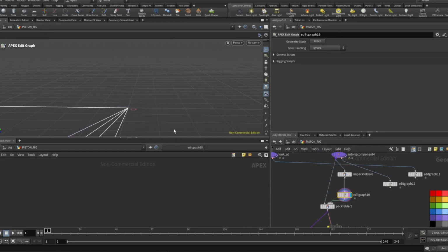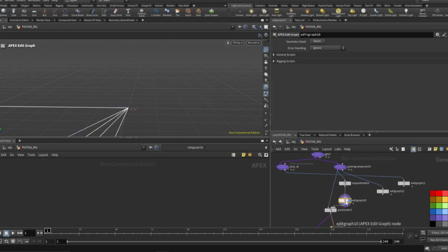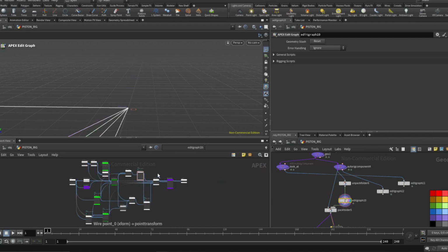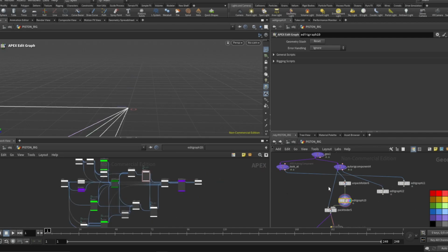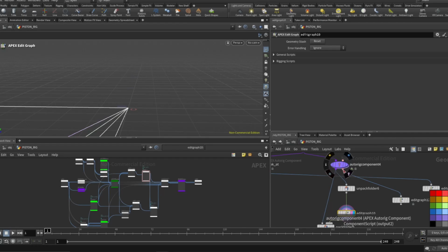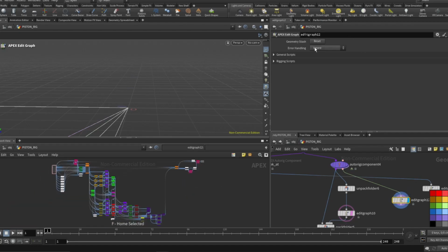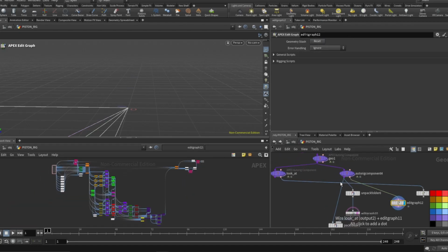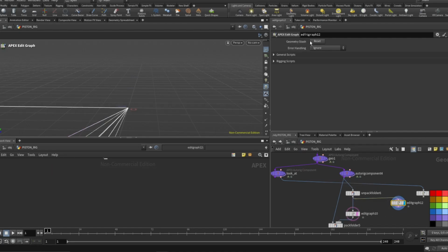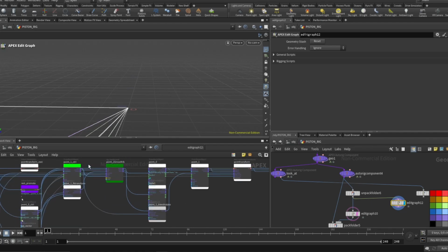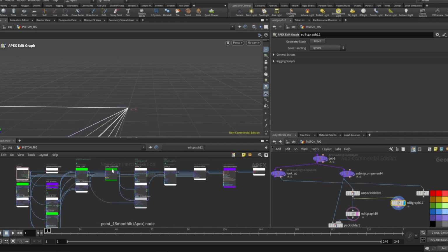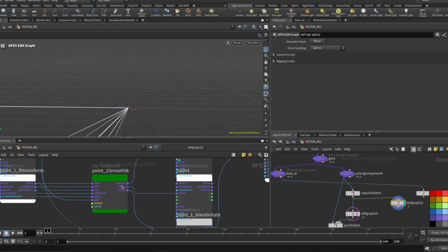But just for the sake of showing what I have done, it's actually taking the second null here from the IK smooth setup. No, I'm sorry, actually I took the first one, and it looks like this. So I checked what we got here, and we have the root, mid, and tip out. As we can see, the mid out doesn't serve anything.